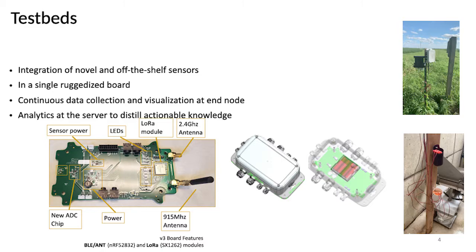In terms of IoT testbeds, we have innovated on the sensor side, on the communication side, and on the data analytics side. We have these kinds of sensor nodes now which package within them the microcontroller, the short-range and the long-range communication capability, and they have an adequate amount of power that they can last weeks and sometimes even months. These nodes have been packaged up such that even if it rains, even if it snows, they will continue to operate and provide us with this kind of real-time data.